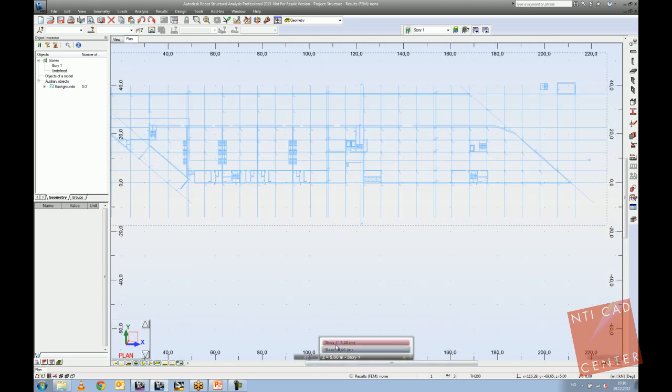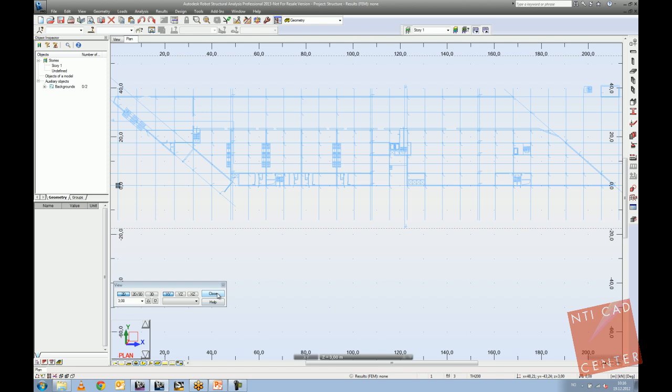If you move to the plan now, you see that I have the possibility to stand somewhere. It has two stories defined as the default ones if I haven't defined anything else. Navigating through this is quite tricky because I cannot just go here and specify where I should go. I would need to use another dialog box by clicking on the global axis, where I specify, for example, at which height I want to stand, like 3 meters, enter, and then I jump to that plane, etc. So that's one way of doing it.